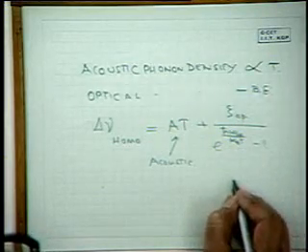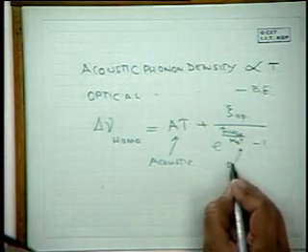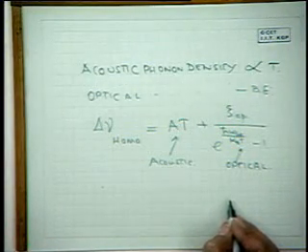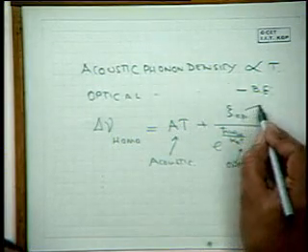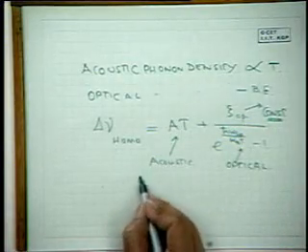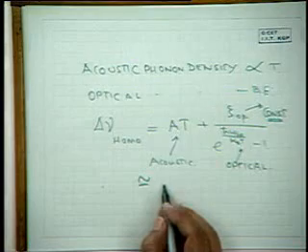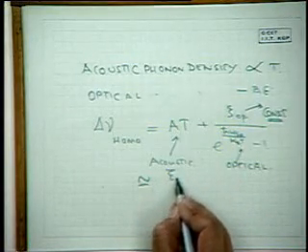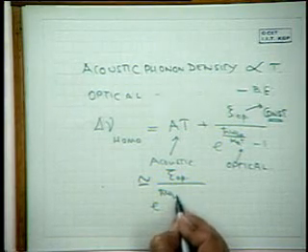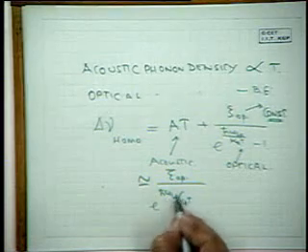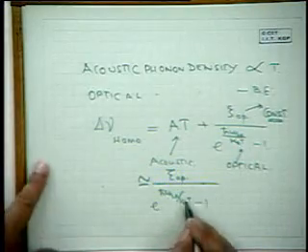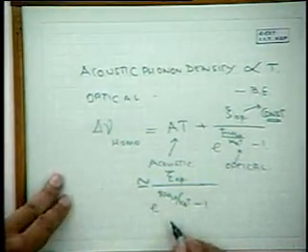And this is due to optical phonons, where xi optical is an optical phonon broadening constant. It turns out that the acoustic term is negligible, so it is mainly the optical phonon term that dominates. Of course, this optical phonon energy, we know what it is for each semiconductor. It is of the order of 40, 50 meV.